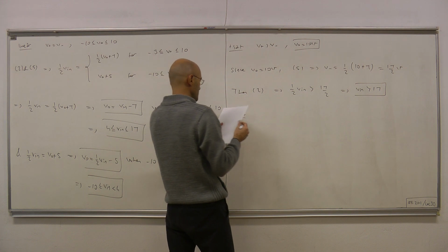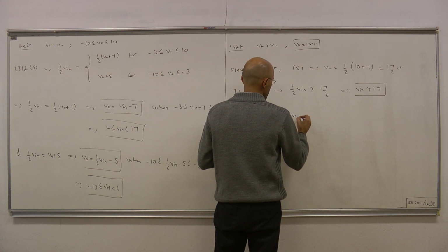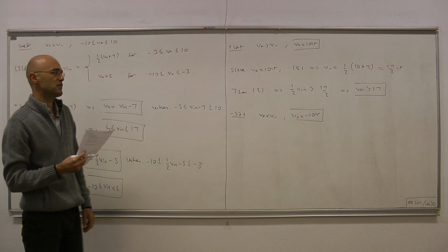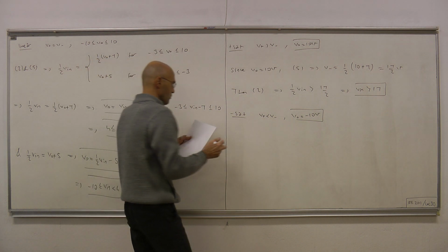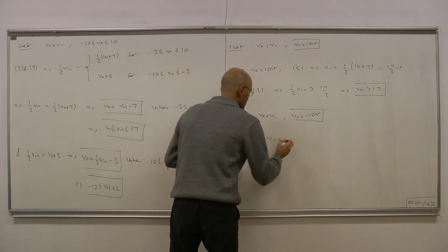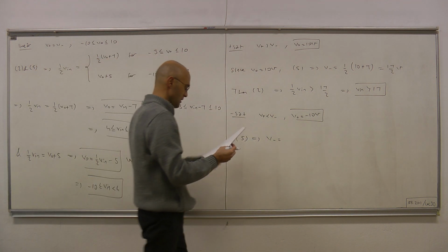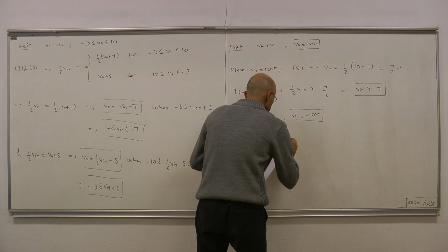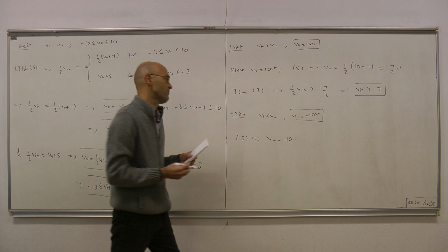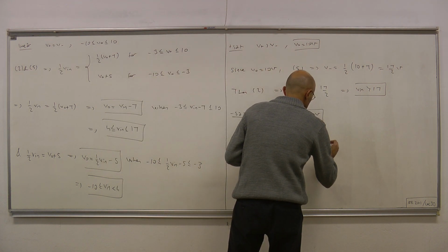As for negative saturation region, we have V plus less than V minus, and V out equals fixed at minus 10 volts. So again, 5 yields V minus equals the second expression, that is V0 plus 5. V0 is minus 10 because you're at negative saturation, plus 5, that yields minus 5 volts.